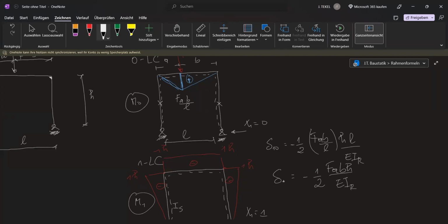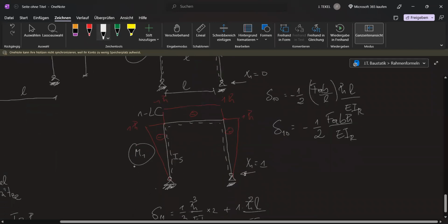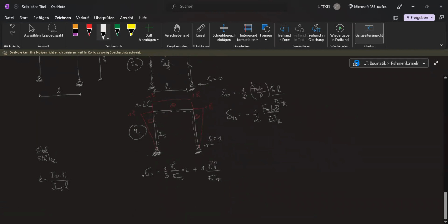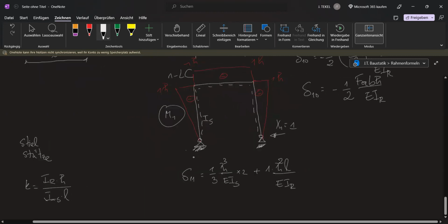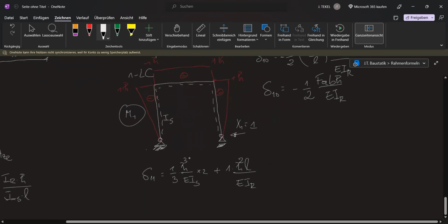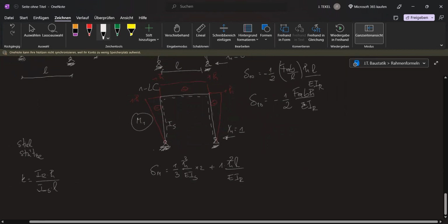There was an assumption in this whole calculation. We've seen it in the above case and in the first calculation we did. The assumption is that the Young's modulus is the same for the whole system, which should not necessarily be the case in real life, right? But that's the assumption here. That's the E. The Young's modulus is the same.